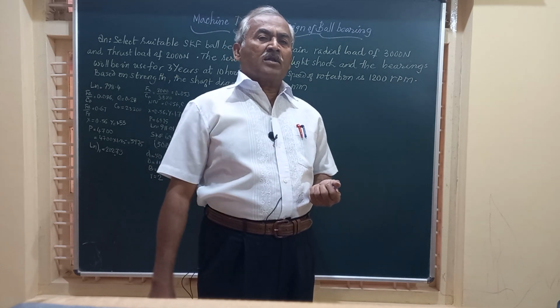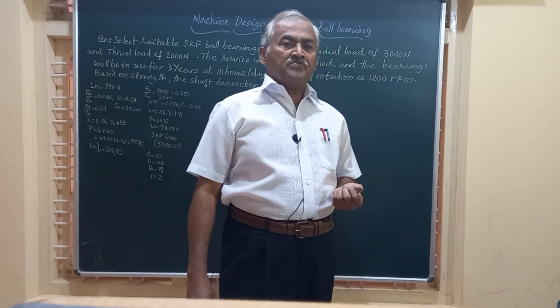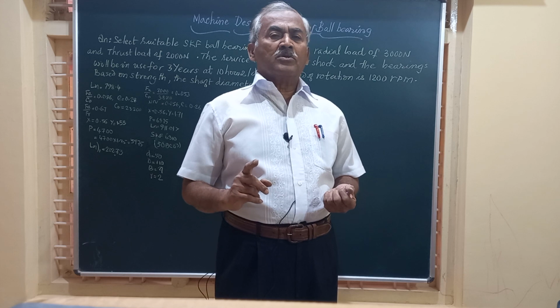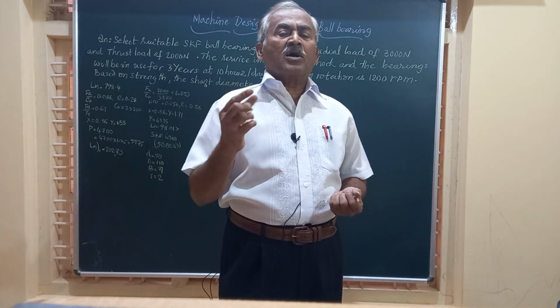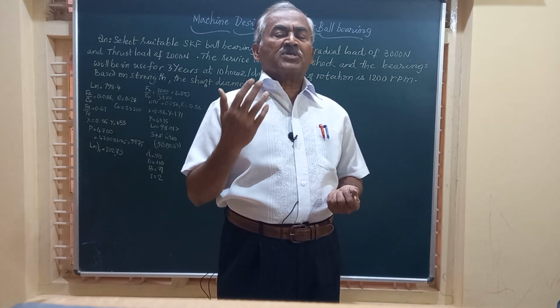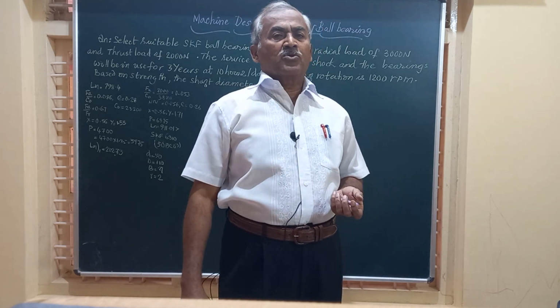in design of ball bearing, we have two varieties of problem. In the first type of problem, based on strength, the shaft diameter or the bearing diameter will be given, and you have to select a suitable ball bearing from the machine design data handbook.